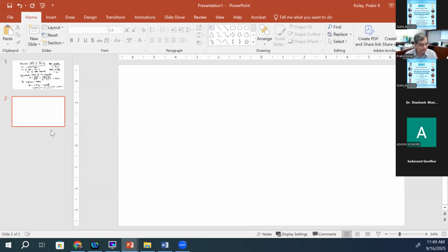I'm so sorry. So then the total discharge you can calculate. Total discharge Q is given by this equation again: pi times K times (HW0 squared minus HW1 squared) divided by ln(Ri divided by R naught).